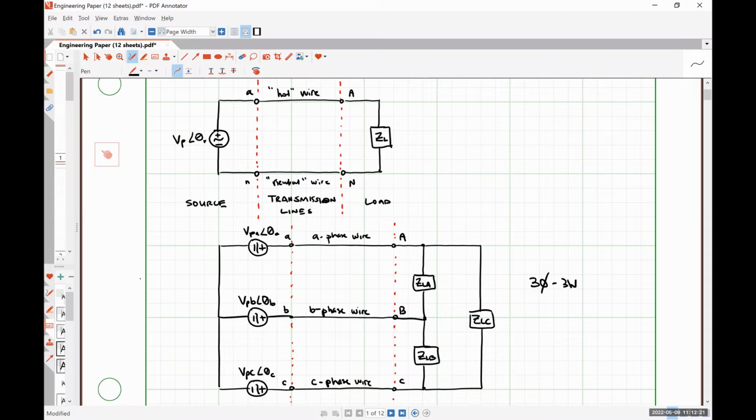There are even some places here in the United States that use higher than three-phase power. Those are typically metal refinery plants. And the reason that they use more than 3 phases is to make it economical to generate enough current in order to melt down metals. For the overwhelming majority of applications, the sweet spot versus simplicity and economic feasibility lies in a three-phase distribution system.